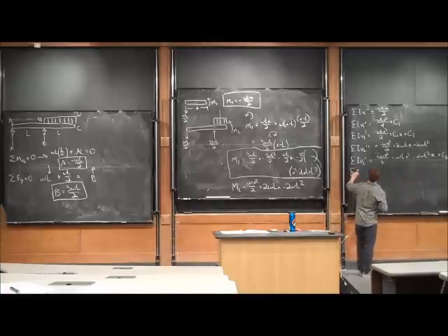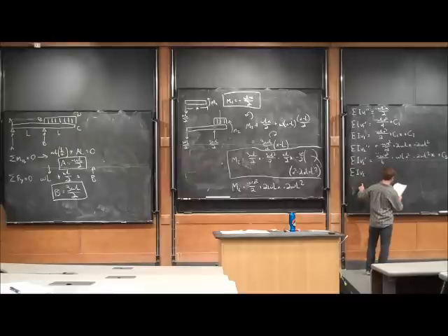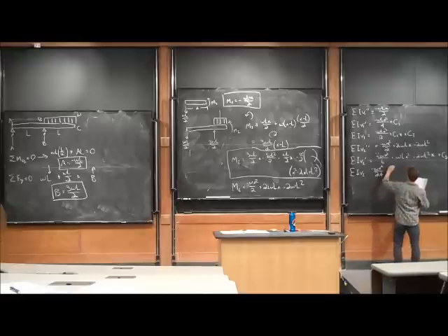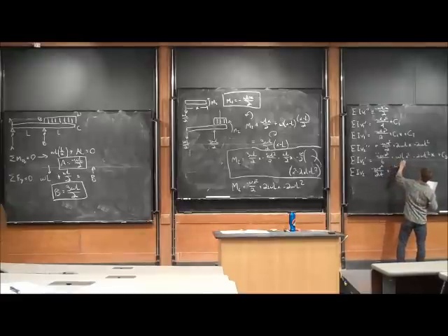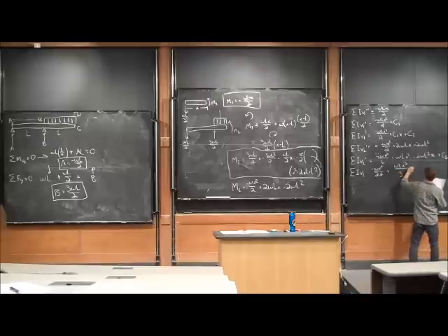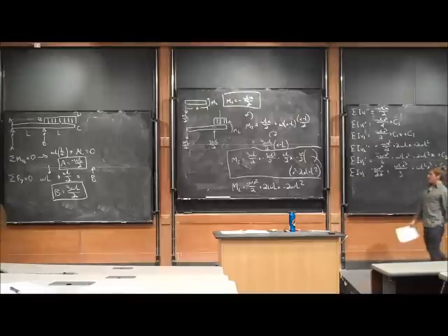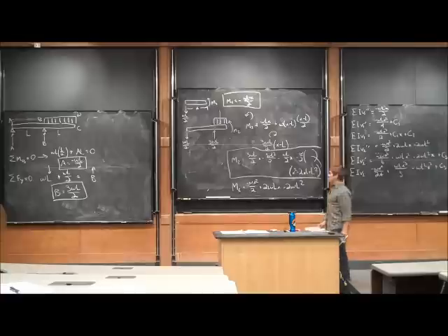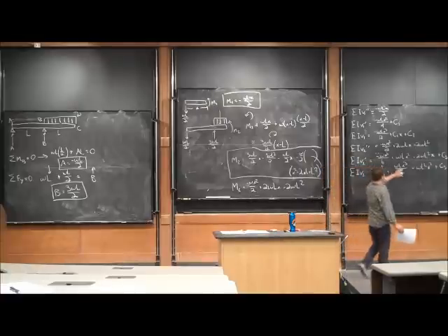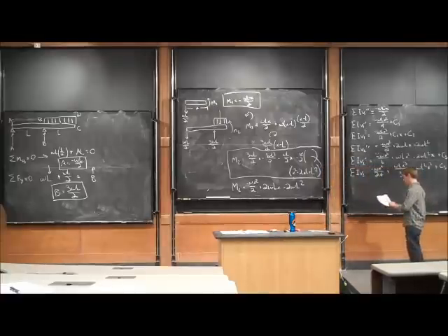And then our deflection for the second portion of the beam is going to be given by negative WX to the 4th over 24 plus WLX cubed over 3 minus WL squared x squared plus C3x plus C4. And now we have to apply our more complicated boundary conditions to find what C1, C2, C3, and C4 are.